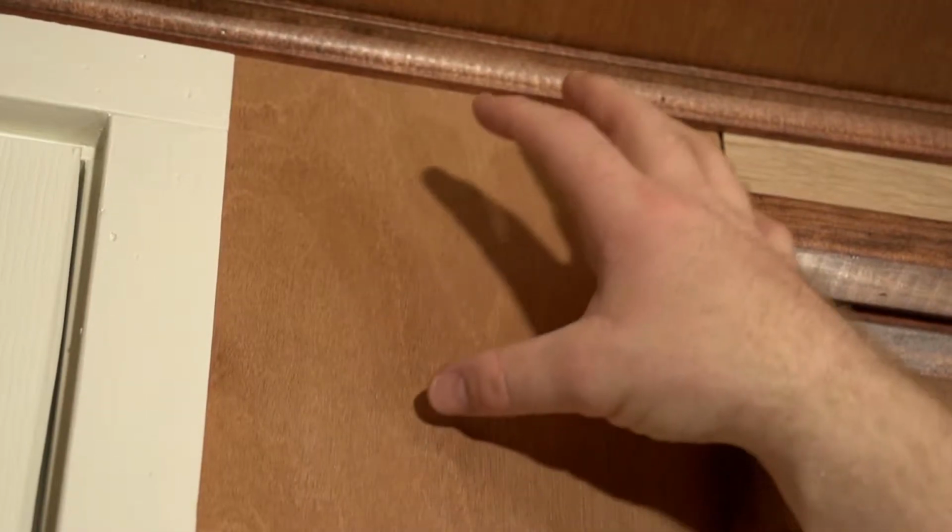Let's briefly talk about some common air sealing problems that we're going to address in a house like this. We're going to start over here. This is an interior wall, and frequently the top plates and bottom plates of this wall are going to have penetrations through them, plumbing, electrical, things like that, and very rarely are those penetrations sealed correctly. That allows airflow from the attic or crawl space into this interior wall inside the envelope, which then usually is going to leak out through other penetrations in that interior wall.